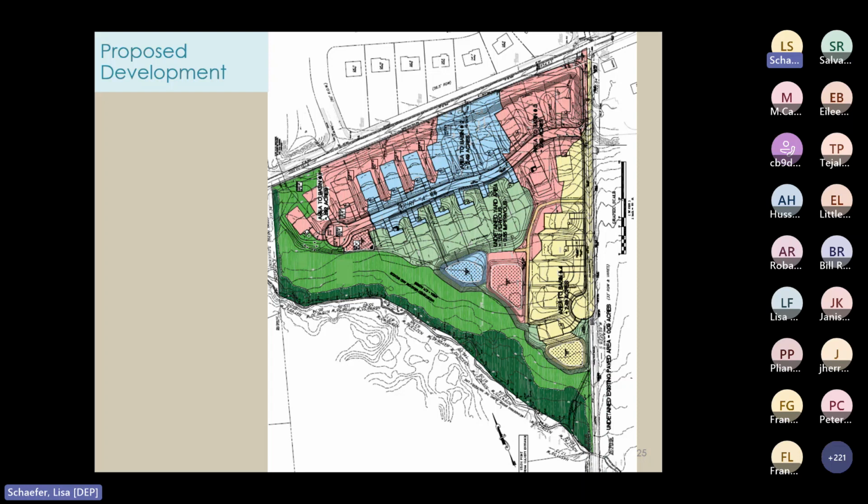All right, so even though the drainage areas are below the contributory drainage limits, none of the BMPs reported as being GI BMPs are close to the source of runoff, nor are they distributed throughout the site. So this layout definitely does not meet the GI requirements. Lastly, I want to mention that there's a lighter green area in the center that has roof area generated runoff. It's not detained, and so I'm wondering how the site is going to comply with the quantity control design and performance standards.